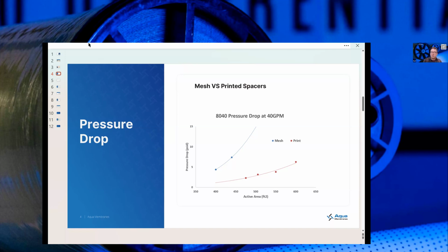Well, when we start talking about pressure drop in the absence of anything else, one of the things that is likely going through your mind is the effect on concentration polarization, because if we wanted to get the lowest possible pressure drop, we would design a channel that goes to a completely laminar flow. But then the idea is that mixing would suffer.